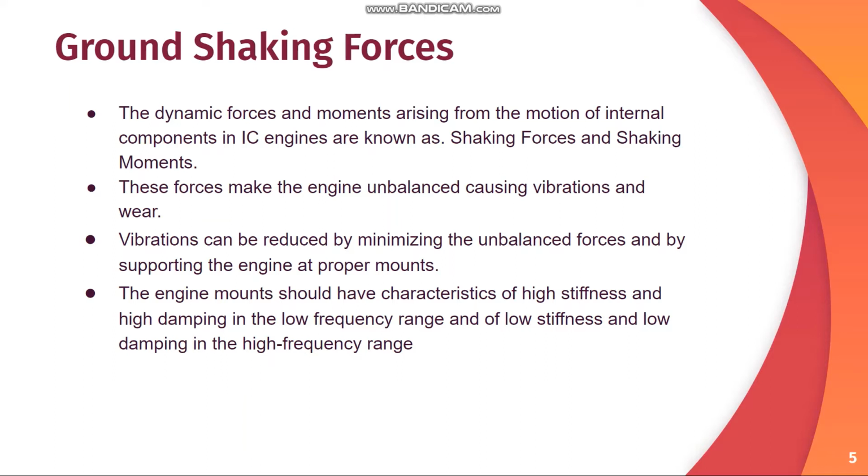The vibrations can be reduced by balancing the engine and using engine mounts of proper specifications. The engine mounts should have high stiffness and high damping in the low frequency range, and low stiffness and low damping in the high frequency range.